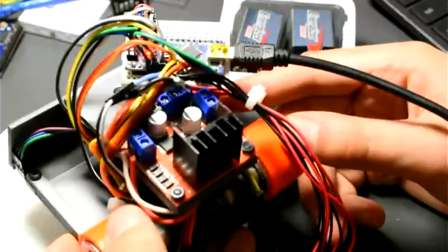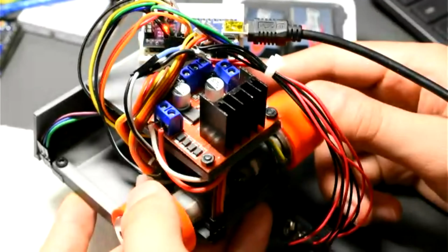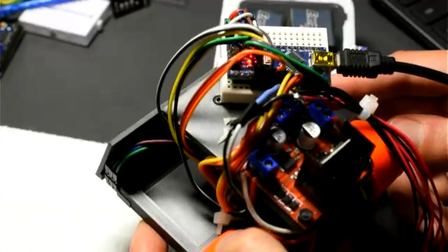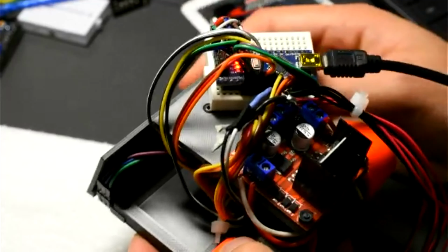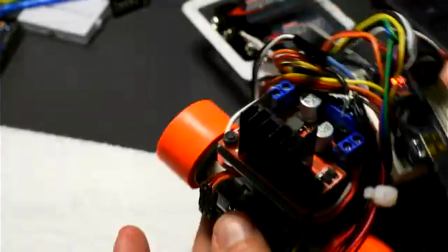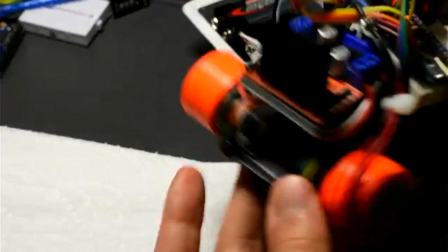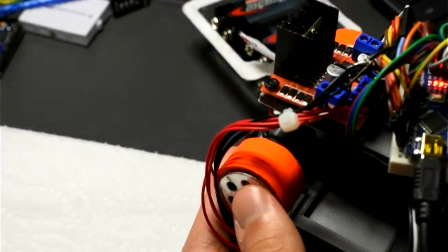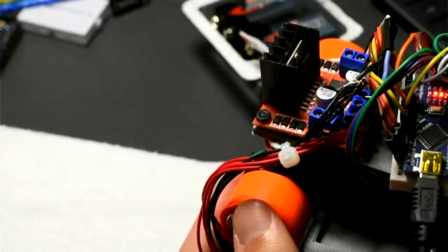And what I'm going to do first is, because we're hitting an edge, we don't want to just turn around immediately because we're really close to the edge. So I'm going to basically say go backwards a bit for maybe a quarter of a second and then turn around. The exact time that I'll make it turn around for is kind of arbitrary because you don't want it to just go back 180 degrees and follow the same path that it just went down, because you won't end up covering the whole playing field. You'll just end up covering that one line.